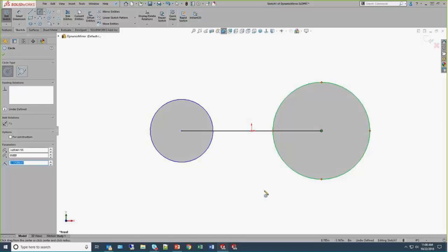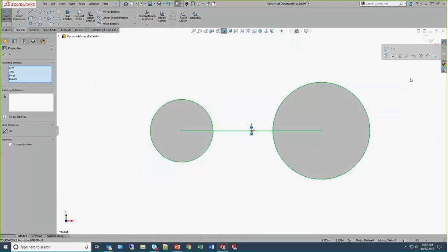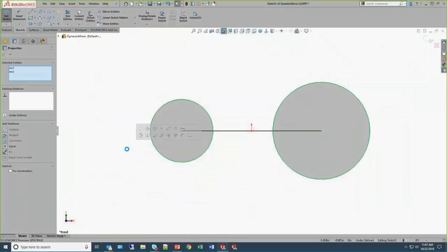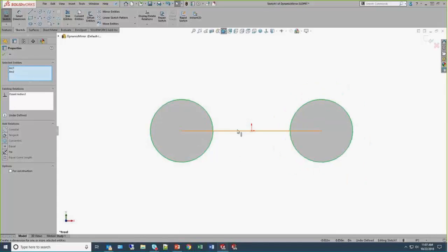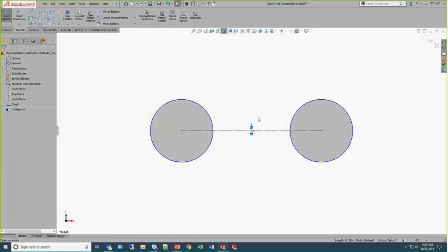And obviously they're not the same size, so this is where I really like to leverage a right to left crossing window. Remember, right to left is crossing, left to right is window. So just a little side tip there. I find myself personally using a ton of window and crossing selections in SOLIDWORKS, and I'm just going to simply make that equal. Another thing that I really leverage are the pop-up toolbars in SOLIDWORKS. Those needed or pertinent commands are always right at the tip of the mouse and makes it much easier than trying to find where everything is inside the UI.